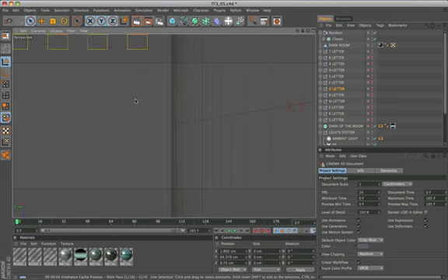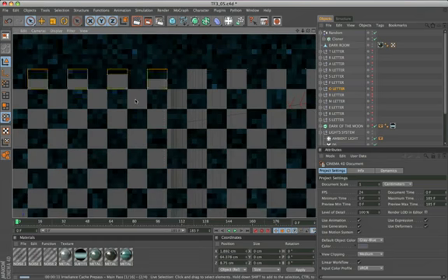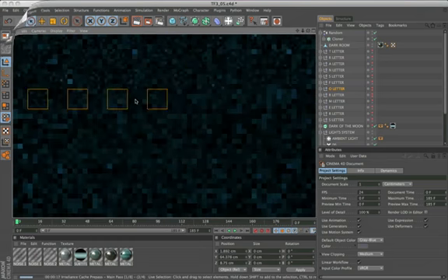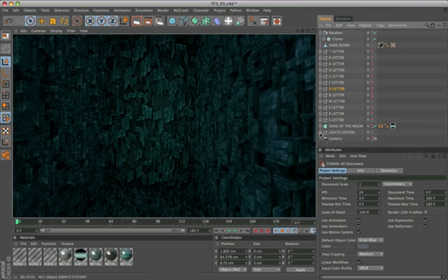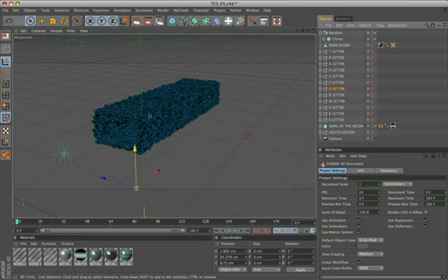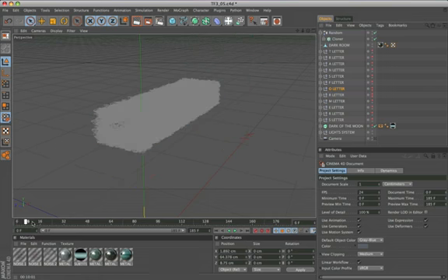Unfortunately, although we have optimized GI, it takes a long time to render our scene. But the result is very cool. Obviously, if we leave 15,000 clones our file becomes very slow to operate. Set this value only for the final rendering.